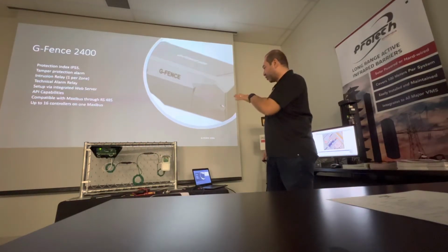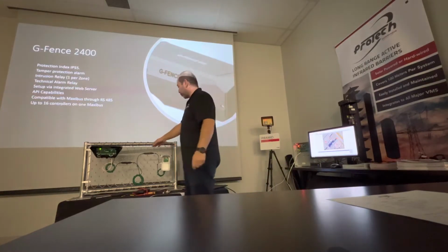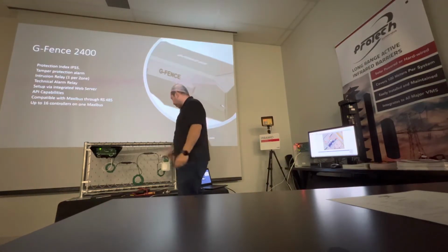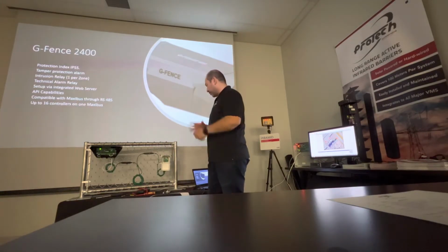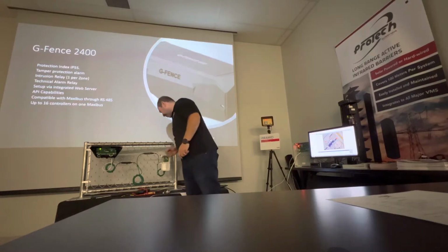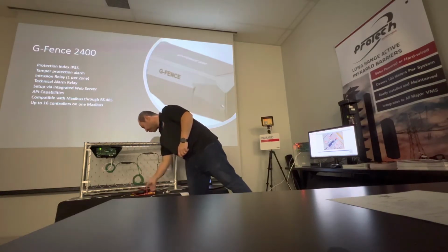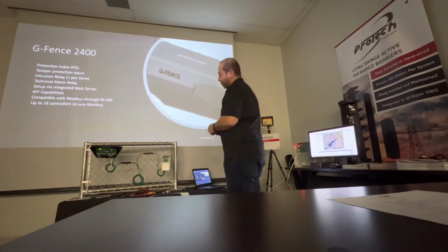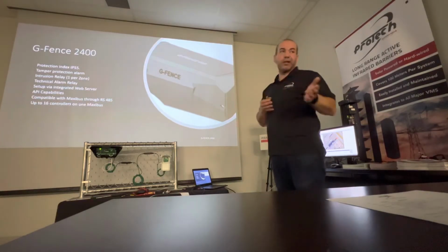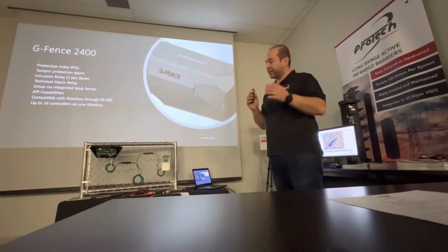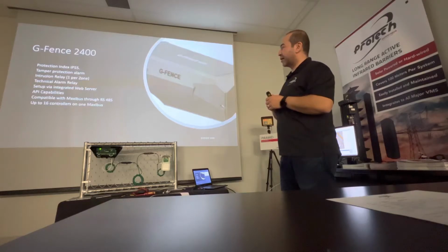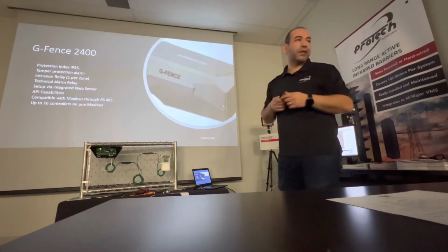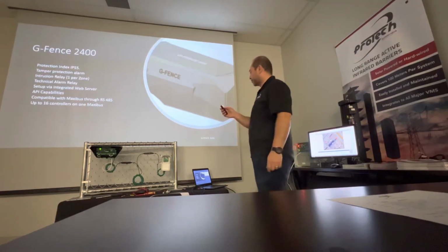So this is what you need. One control unit, a couple of rolls of cable, depending on the length of the perimeter, a couple of link boxes, UT or UR, up to 6 for a total of 600 meters. Then screwdriver, stripper, multimeter, just to measure the voltage. The voltage can be 12 volt DC or 24 volt DC. There's no problem. Usually, some installers need to use the same power as the alarm panel, so 24 volt DC will be perfect, I guess.